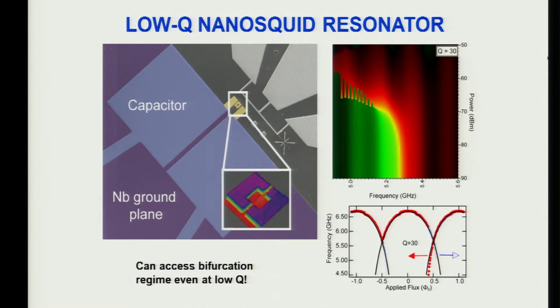One thing I want to point out, and perhaps not dwell on here, is if you look at the tuning of this squid curve, there's something strange. It's actually hysteretic, even though it was not hysteretic in the DC IV characteristic. So the inductance properties of this device are actually quite interesting and very understandable if one spends a little bit of time on it. So we have now a device which tunes with flux. It's a squid, and we can measure small magnetic fields with it.